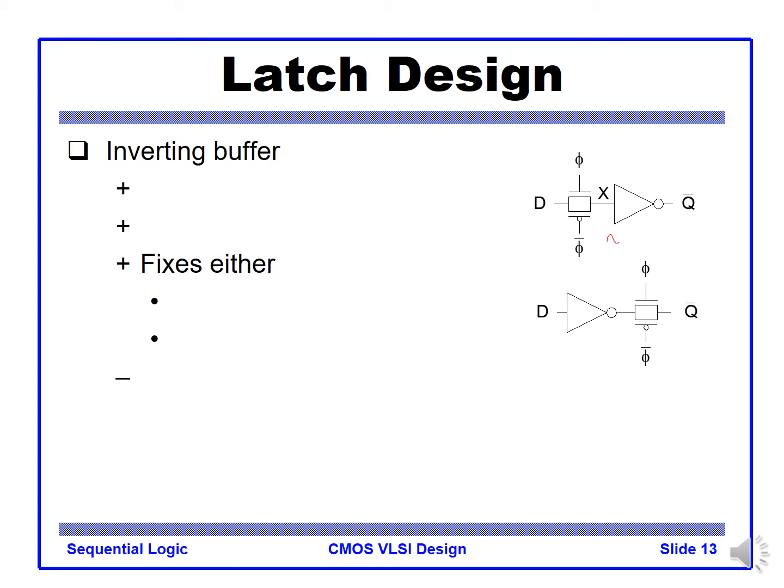To resolve the restoring capability, we can add an inverter so that the input data X is recovered to either VDD or ground, right? You may have a choice of adding the buffer at the output or input.